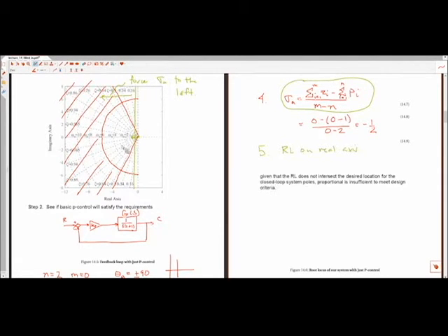So the farther that I try and push closed loop pole locations, say move them to the real axis, that means considerably higher gains in our system, which corresponds to a bunch of negative effects such as noise amplification, et cetera, that is going to make it difficult for you to design controllers even theoretically, but practically speaking, it's going to cause a lot of issues as well.